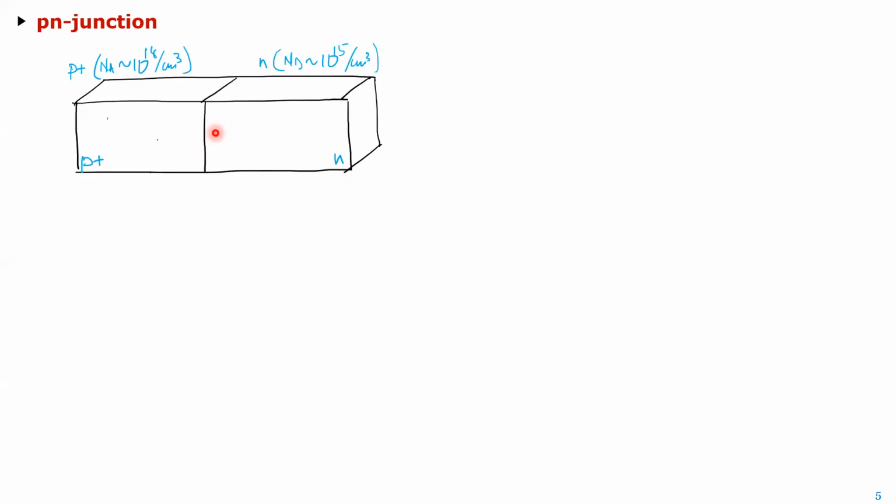And when you take two of these semiconductor materials whose electron energies are different, and you join them, for example, in the n-type, the electron energy is higher than the p-type. So what will happen is they'll start moving from this direction to this direction. But as they're moving, they keep leaving these immobile positive ions behind, which will create an electric field between this end to that end, and it'll keep happening till this electric field can fight back the potential difference which exists between a plane P plus and N plus.